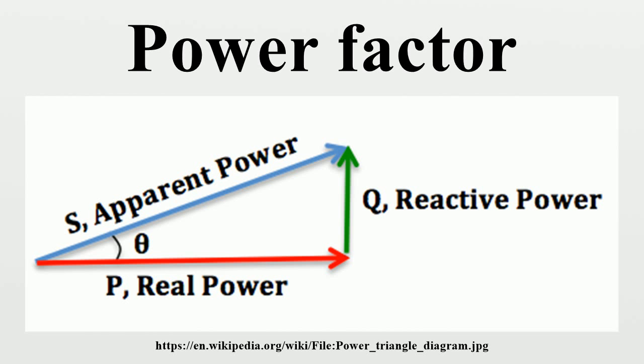An automatic power factor correction unit consists of a number of capacitors that are switched by means of contactors. These contactors are controlled by a regulator that measures power factor in an electrical network, depending on the load and power factor of the network. The power factor controller will switch the necessary blocks of capacitors in steps to make sure the power factor stays above a selected value. Instead of using a set of switched capacitors, an unloaded synchronous motor can supply reactive power.